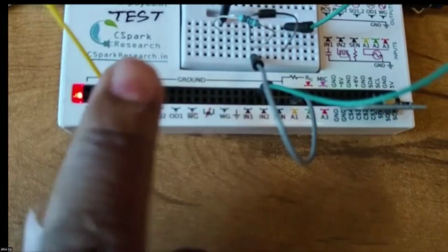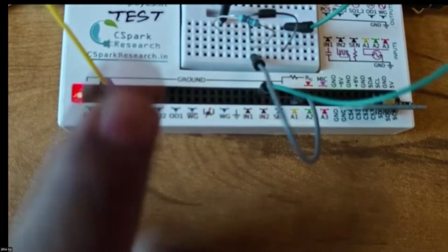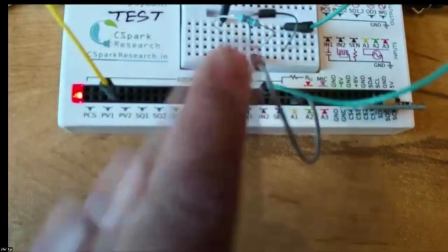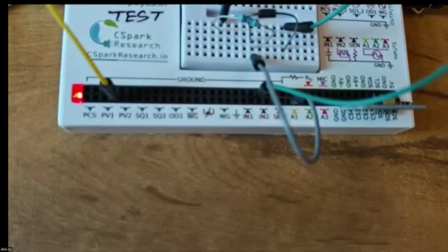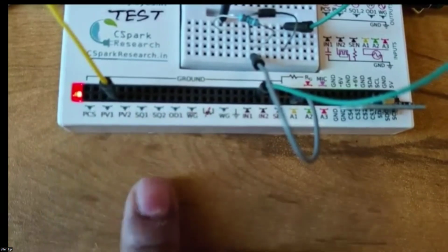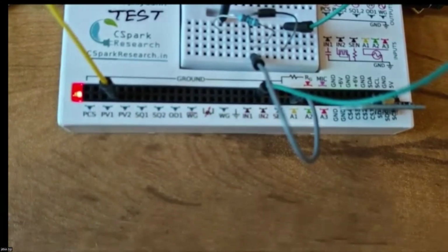And the same current has to flow through this diode also. Kirchhoff's law. It cannot escape anywhere else. If it is going through this resistor, it also has to go through the diode. So now you have V and I both. So you just keep changing PV1 values in steps and you plot. So let's see what we have done here.